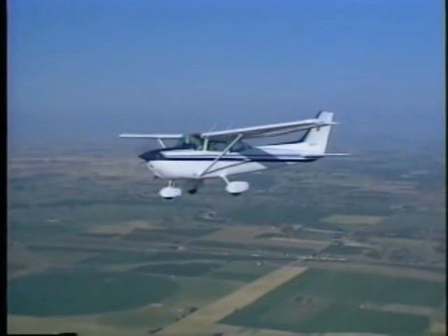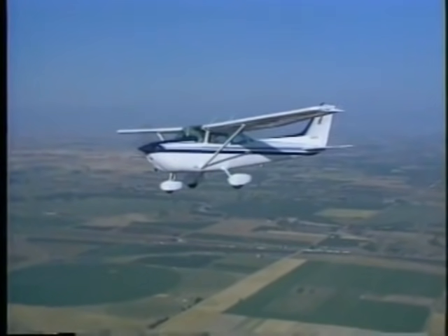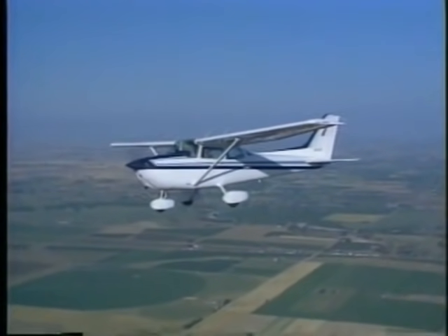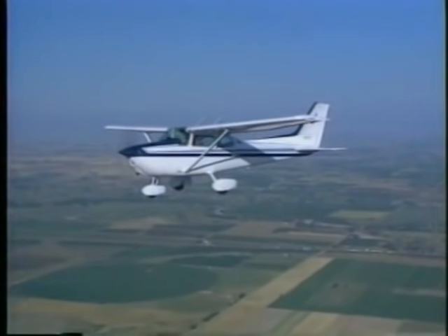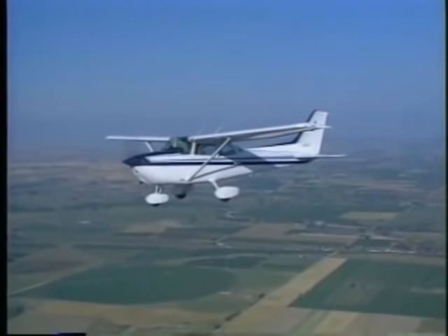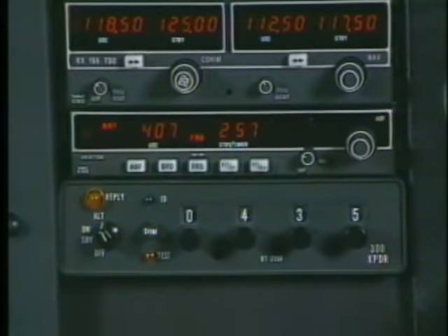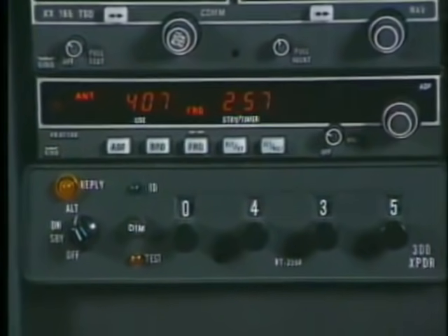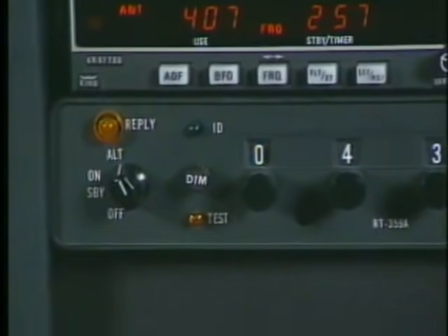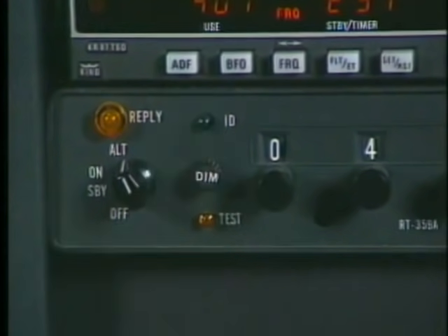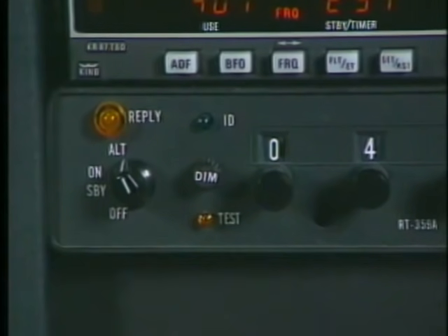While not mandatory, you are strongly encouraged to establish and maintain communications with ATC when operating within the 20-mile outer area. To fly within Class C airspace, your aircraft must be equipped with an operable Mode C transponder. This requirement also extends up to 10,000 feet MSL above the lateral limits of this airspace.